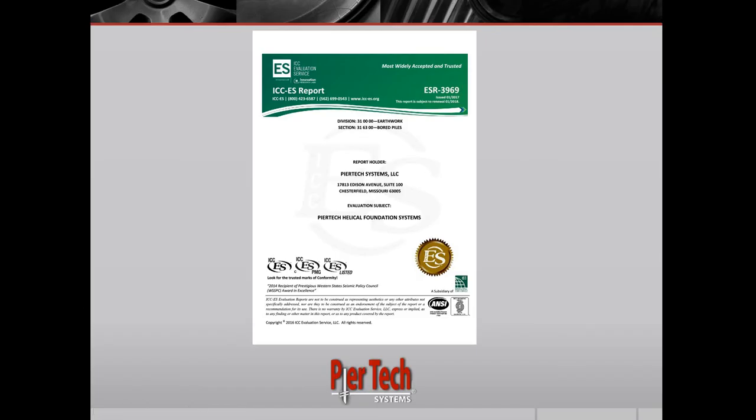All right, next we have material requirements. Sometimes a project may require an independent code council report, evaluation service report, called an ICC-ES report. This is an independent third-party accreditation company that certifies a building product for use in certain applications.